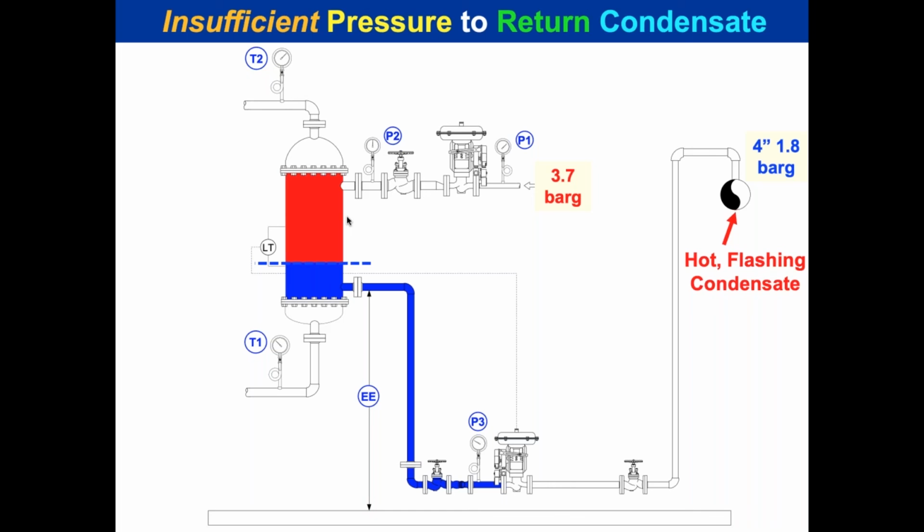And it's hot flashing condensate around 130 C. And here you've got an oversurfaced low pressure heater, which only has 0.35 bar in that reboiler. So down there, your pressure differential from 0.35 bar through that control valve to the outlet line is a minus 1.45 bar G. There's no way that's going to flow.